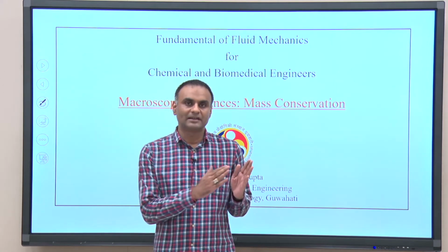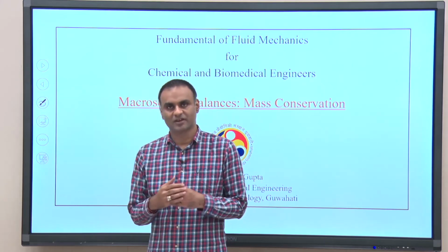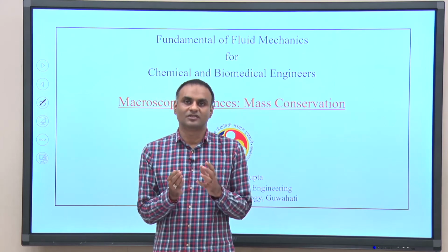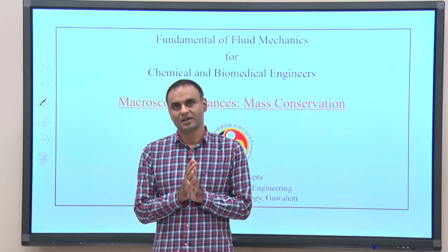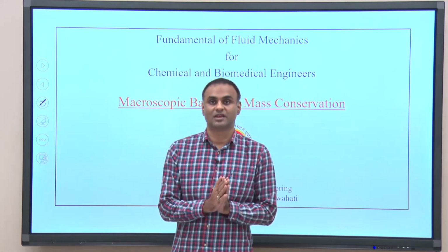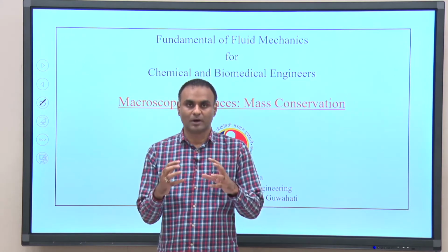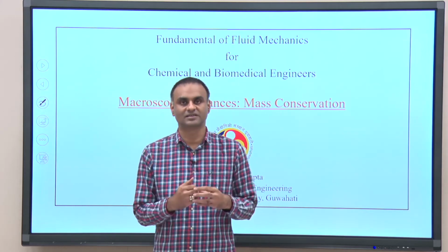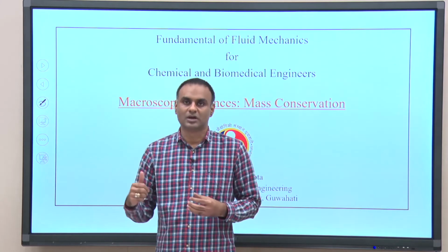We could relate the control volume formulation with the system formulation, whereas the system is an entity which is a control mass, that is a fixed quantity of mass, whereas in fluid mechanics or in this course we are generally dealing with a control volume approach, where we have a control volume, a fixed region in space or a specified region in space through which the mass can come in and go out.